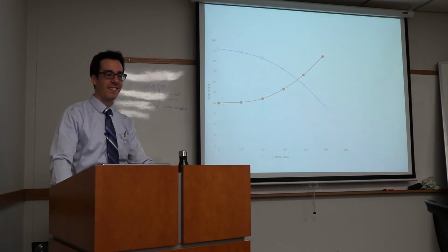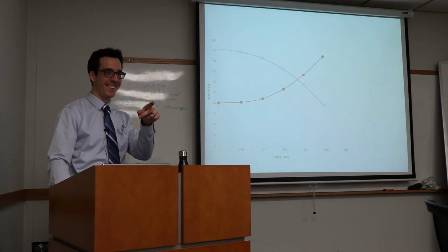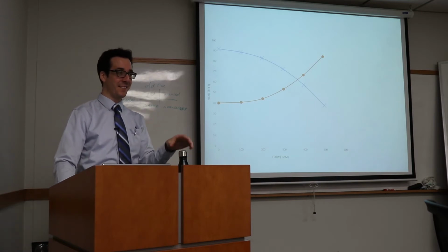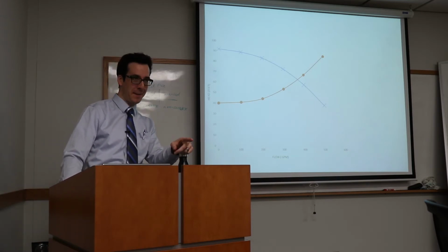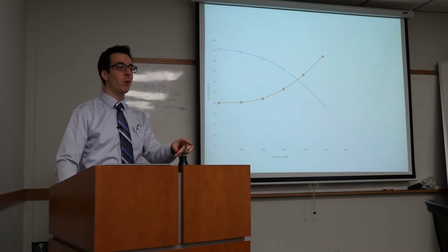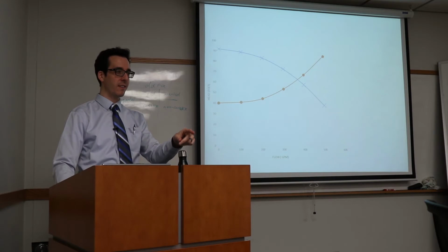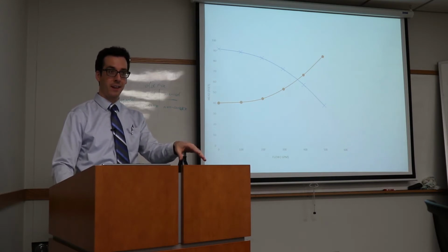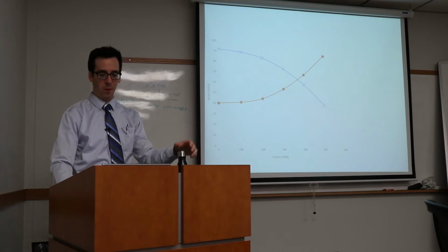That's where it's going to run. You were going to say it's the optimal point. It may or may not be the optimal point; we'll come to that later. But that's where the pump will run, where the pump characteristics match the hydraulic characteristics. The system curve intersects the pump curve, right? That's where the pump will operate.